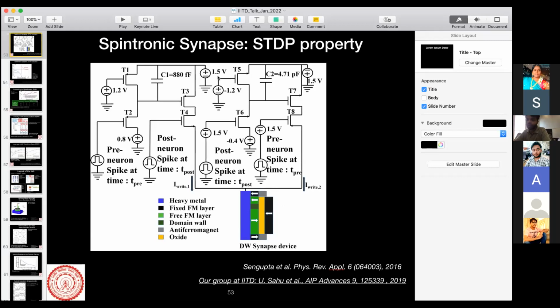So one advantage of spintronics is it's CMOS compatible, as in you can have spintronic devices with transistors. That's why people are thinking about using STT-MRAM in cache memory. Because cache memory has to be CMOS compatible, right? Because cache memory is on the same chip as the rest of your circuit, right? On the processor, right? Okay. Yeah. Okay, sir.